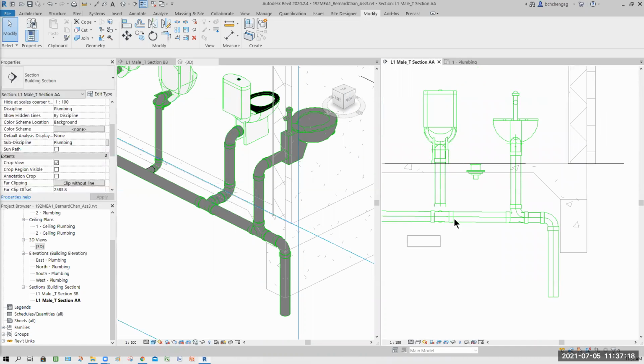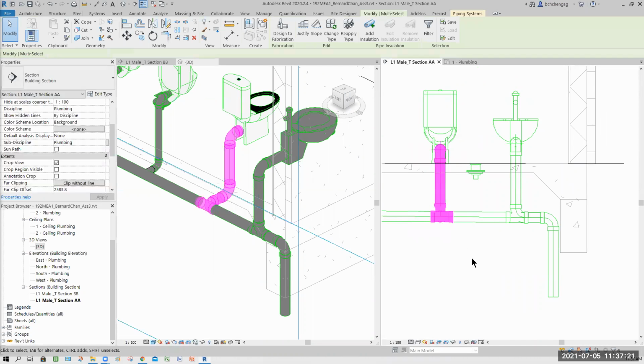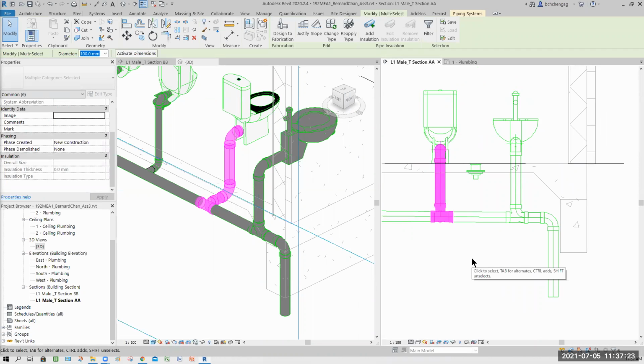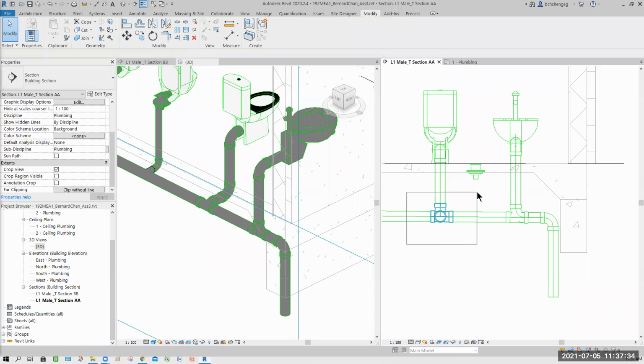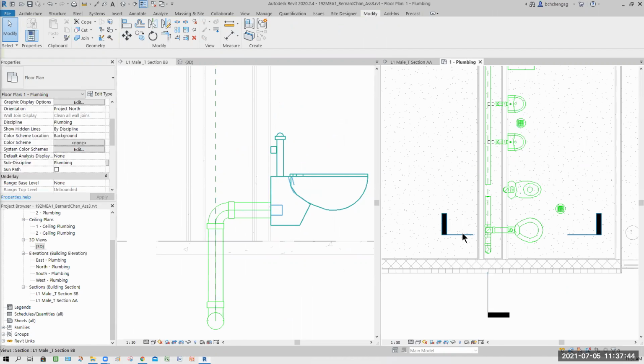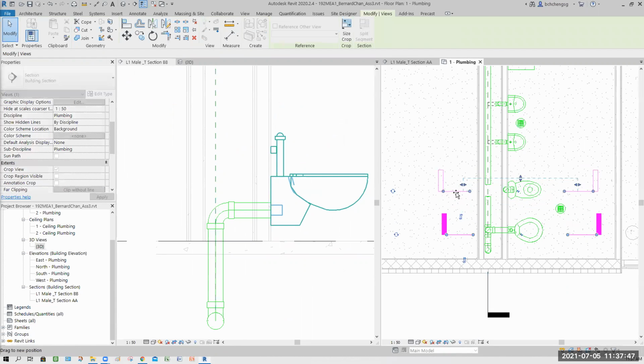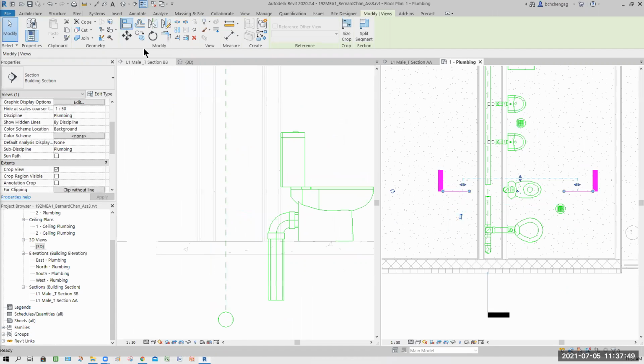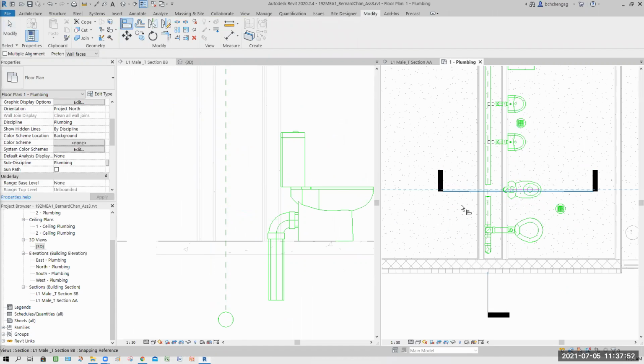Here, I will delete this away. If I can, I try not to delete. Why? I delete partial. Delete partial means only this part. But I need to observe something first. Is there a pipe on this side? So you can see that slowly, I have to move this to adjust it right to here. You don't estimate this way, you use the align function. Align it nicely, then your view will be updated.